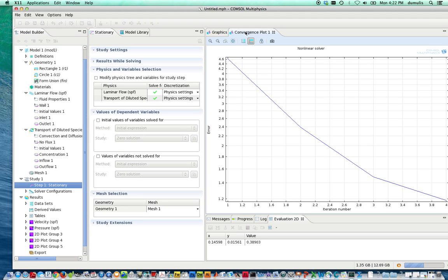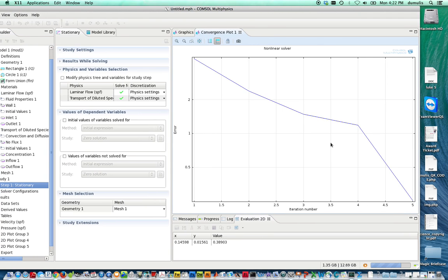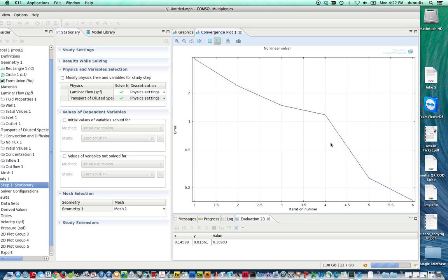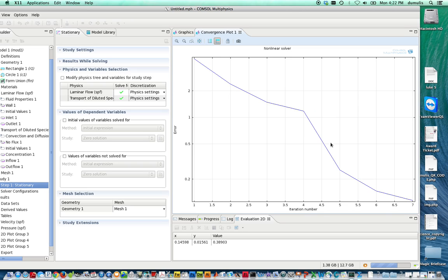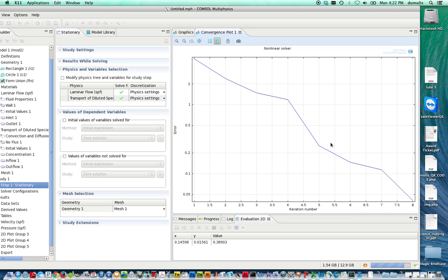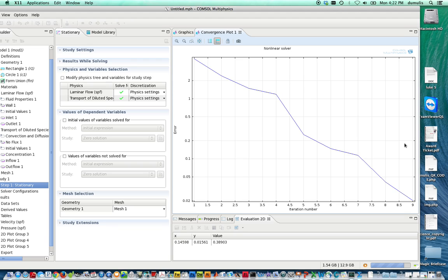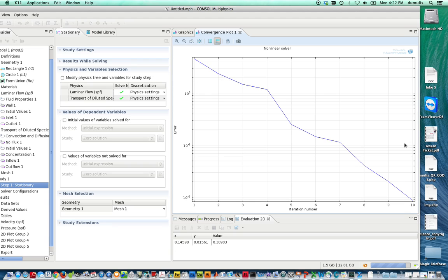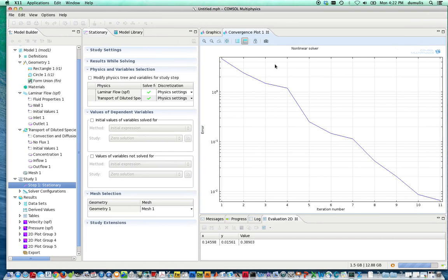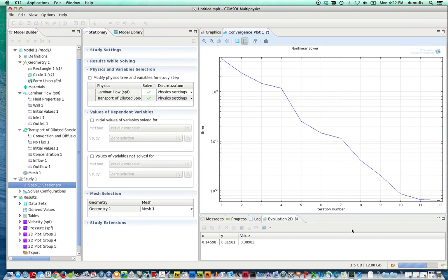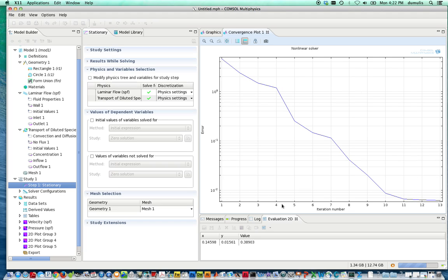Let's check the convergence here as it's running. It probably will take a little bit longer because diffusion has this effect of smoothing things over, and when that goes away, it typically takes longer to do a run. It becomes more of a stiff problem. Numerical stiffness is a problem when you're solving the nonlinear equations. It should be settling down to a solution here in a moment.